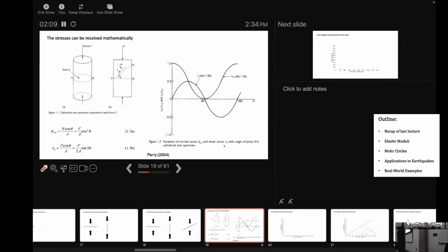So the shear stresses clearly have a range. There's a maximum shear stress and a minimum shear stress, right? Does that happen at 45 degrees? No, it doesn't. In this, it looks like it does. Oh, actually, yes. The shear stress maximum happens at exactly 45 degrees, but the ratio is what we care about in terms of fracturing. And so the ratio of the normal stress to shear stress becomes most optimal at 60 degrees. Yeah, like you said.